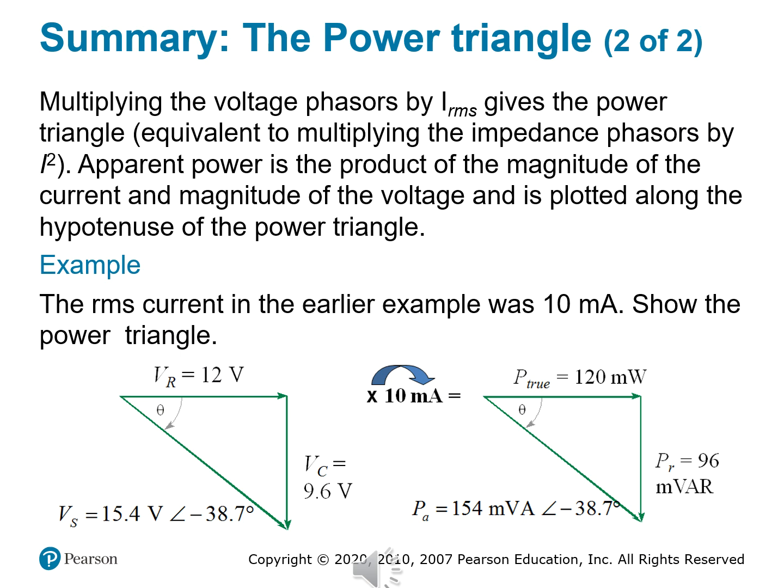So there is a sequence though. You multiply the impedance triangle by current, that gives you the voltage triangle. You multiply the voltage triangle by current one more time, that gives you the power triangle. And each time the triangle shape remains constant, but the scale and the units change. That's all. Right? So wrapping this up, the power triangle is your forensic report of an RC circuit.